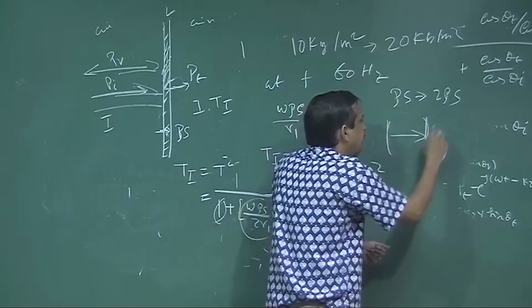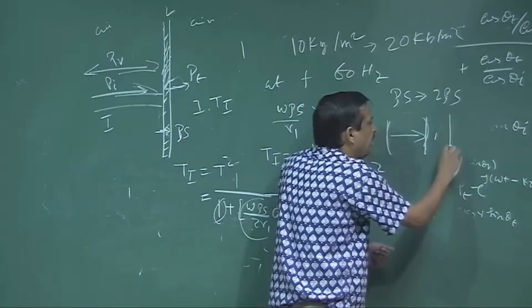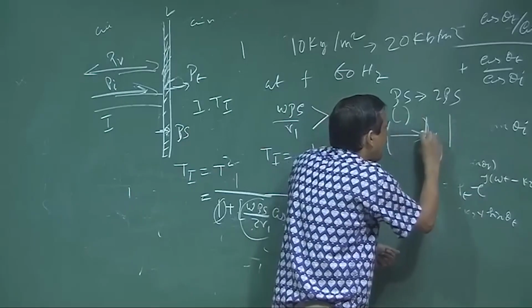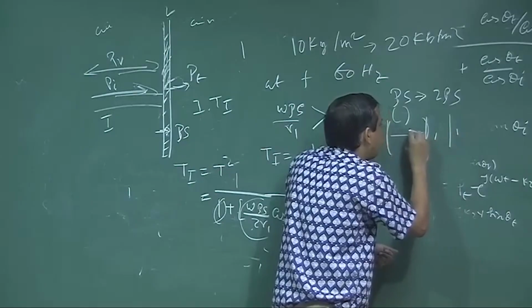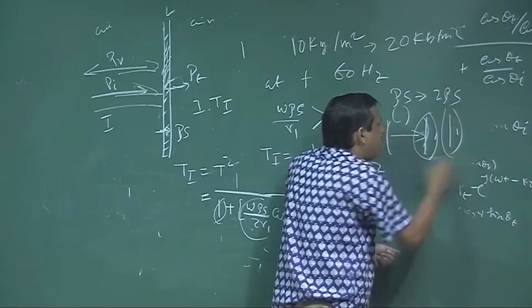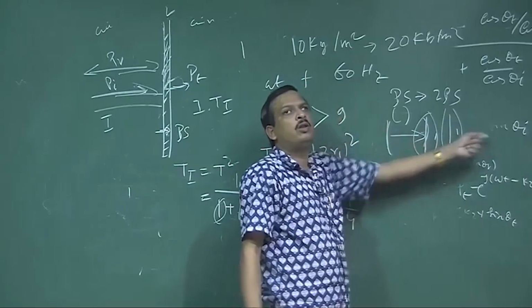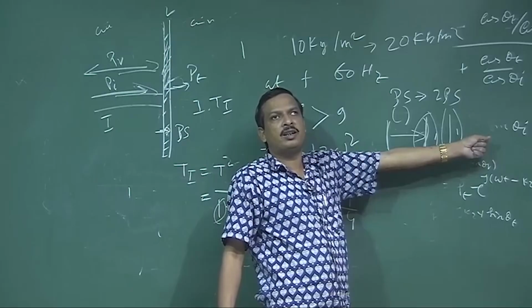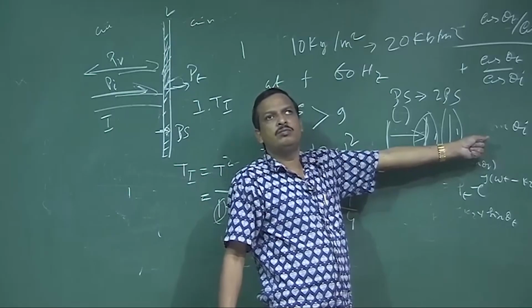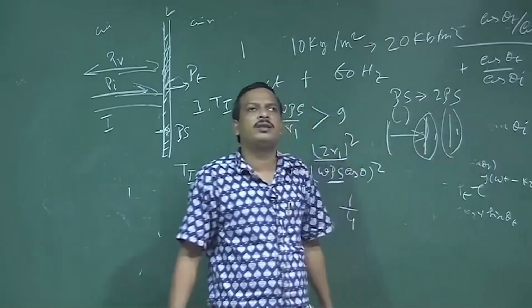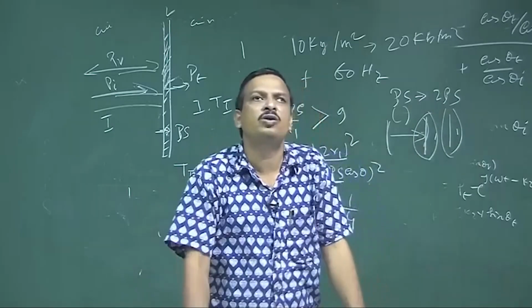If it is glass, then air, and again glass, then the outside noise cannot go inside, because there will be a mass law effect in the two walls. So, inside the auditorium, if two separated glass doors are used, very little outside noise will enter. That is why this is mostly used in architectural acoustics.